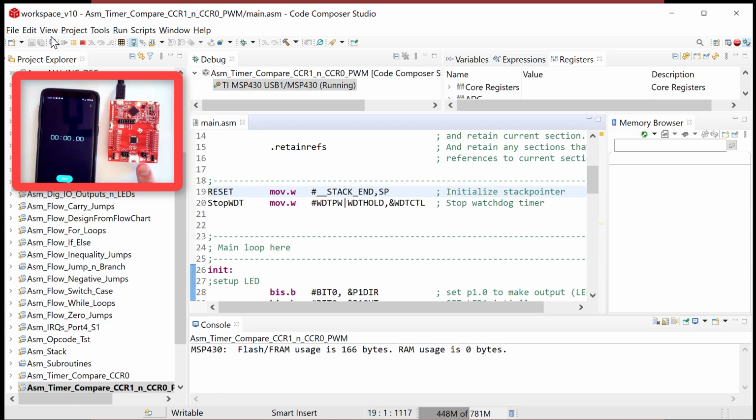Yes, look at this. So look at that little flash. 5% of the time. That's 50 milliseconds, okay? And now you think, I want to see if the period is right. So as soon as it hits, I'm going to go. Look at that. So the period is 1 second, and it's flashing 5%. Now that's 50 milliseconds. You're like, I can't even believe I can see that. What's actually happening is you drive that LED, and it's got a little capacitance in it, so it stays on probably longer than 50 milliseconds. But the signal that we are driving to it is indeed 5%.